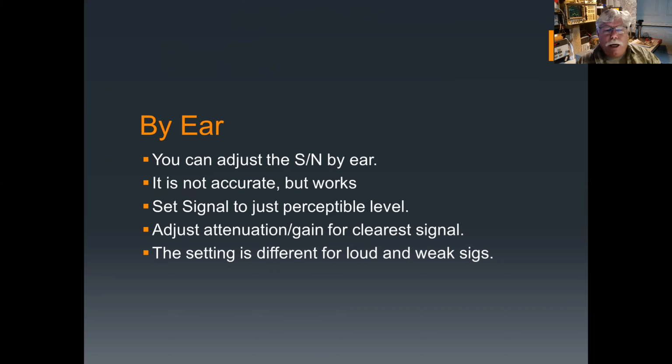In the past, in radios like the FT-790s, 290s, 290R, the older radios, the ICOM 736 radios and all that, the front ends are dual gate MOSFETs, 3SK51, that kind of thing. And those little guys overload really easily. So if you feed too much RF signal in from the converter into the radio, you'll overload it in a heartbeat. I need to tell you that the 7900 was almost impossible to overload. It's a tremendous radio. It's night and day. And you've got the same problem with the FT817. You've basically got a dual gate MOSFET in the front end. And as soon as you get signal levels up, the thing starts to fall apart in terms of operation for exactly the same reason.